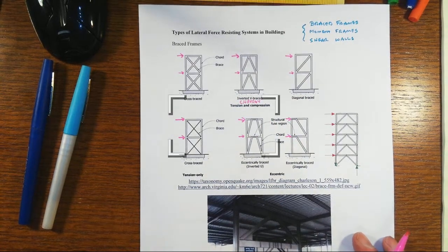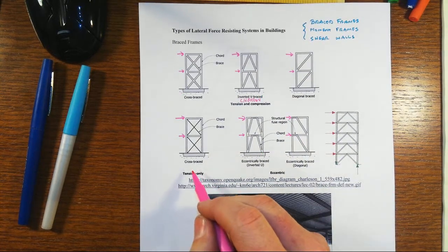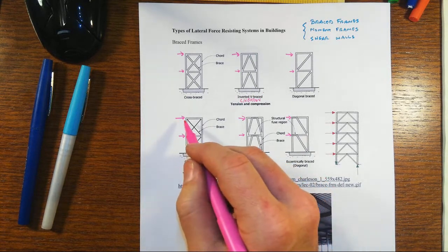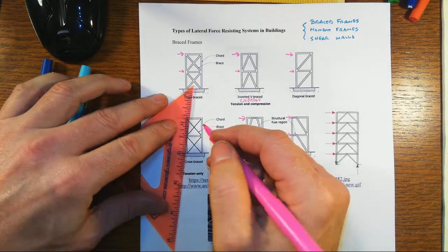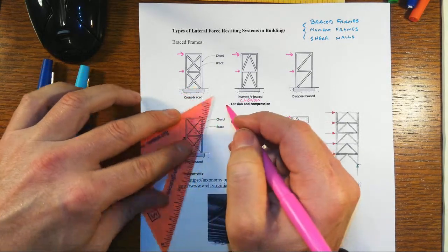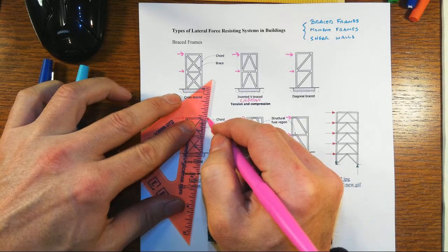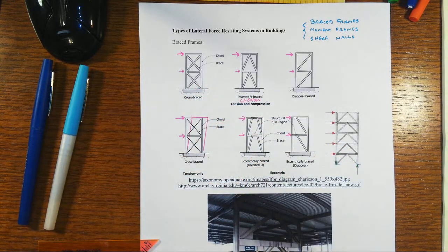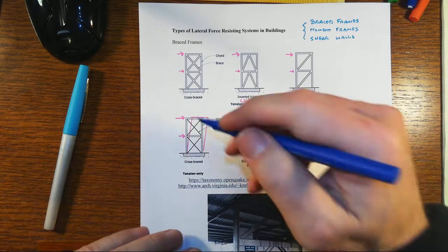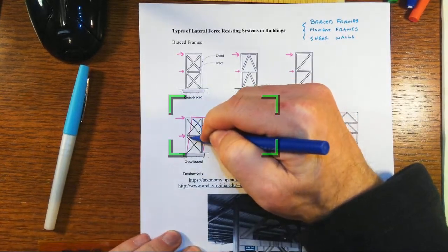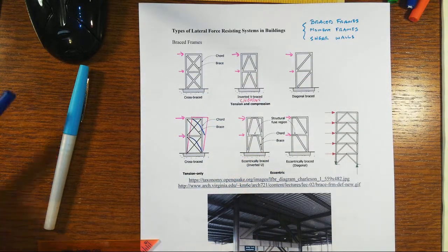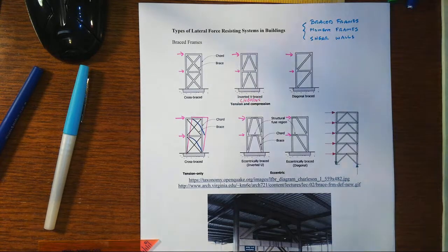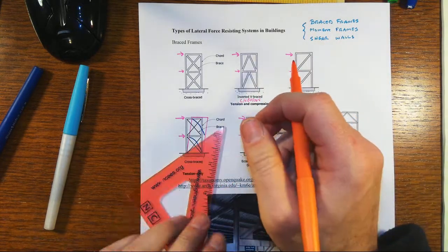Whereas a system that you don't see a lot around is just the simple tension-only or tension counter cross bracing system. When you're pushing with the lateral loads and the system wants to deform, in this case as shown with the loads, skewing or shearing to the right, that would want to cause this middle brace to buckle, because it would be in compression, this middle brace being the one going from upper left to lower right, and then the other one would be in tension.